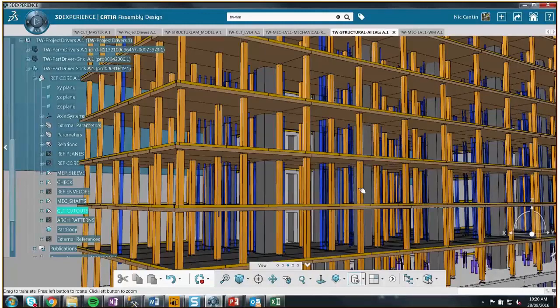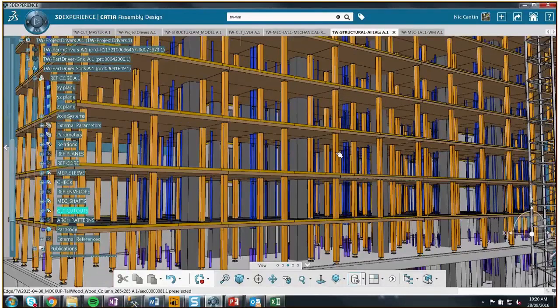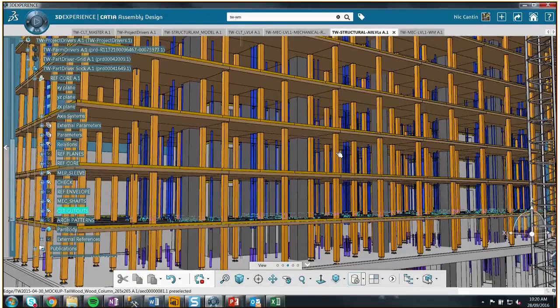Anyways, on the cores, there's angles for the CLT to sit on. And on site, they were surveying every week. I think Nick would be better in our office to answer, but when they had to move an embed slightly or make an adjustment, they were surveying as they went. Whether it got implemented back into the model every time, I'm not sure, but we were aware of it. It was coming out as live pictures and survey data to make sure that when the CLT connects to the core, it was going to fit.